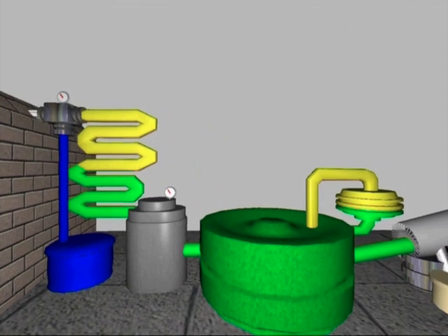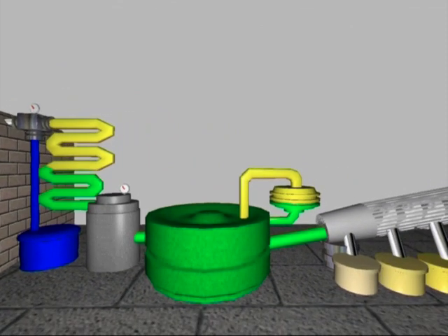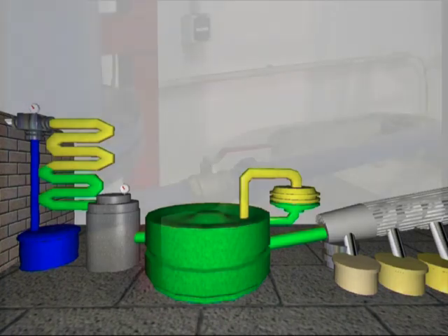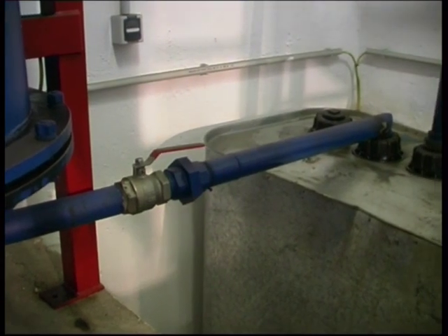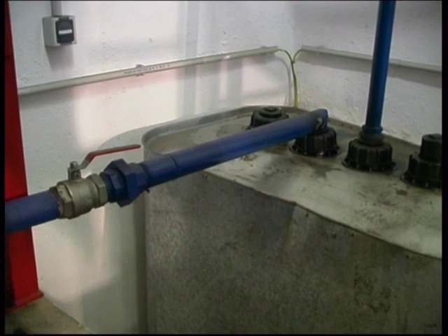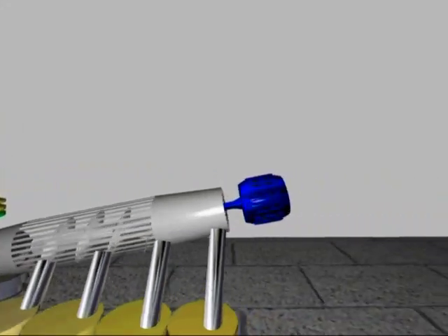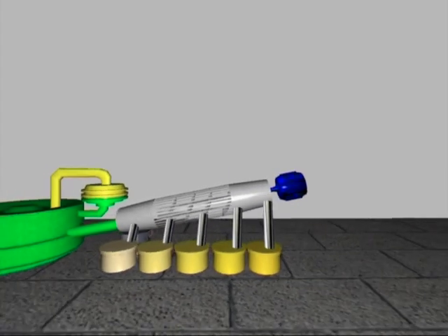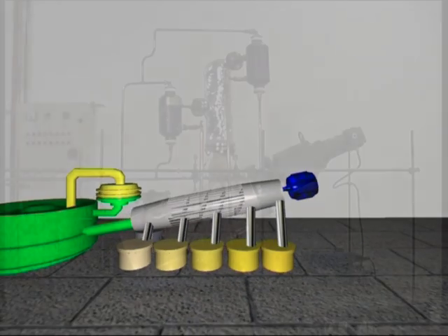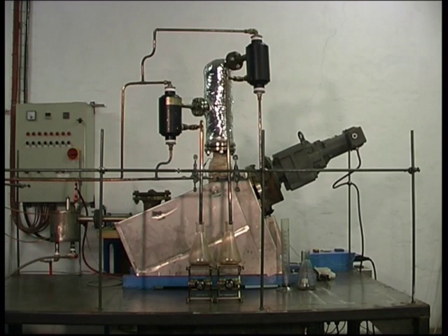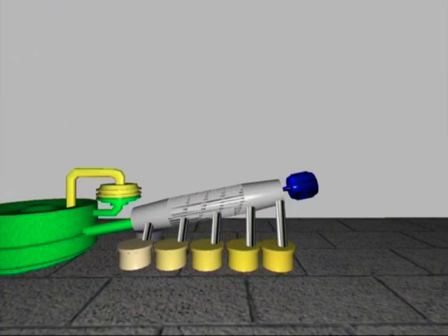Because it is a closed system, escaping tail gases from the storage basin are conducted through filtering equipment and they are cleaned according to emission regulations. The cracker, which follows after the storage basin, extracts the oil and separates it into petroleum, gasoline, kerosene, diesel, and fuel oil. These different substances are conducted into separate tanks.